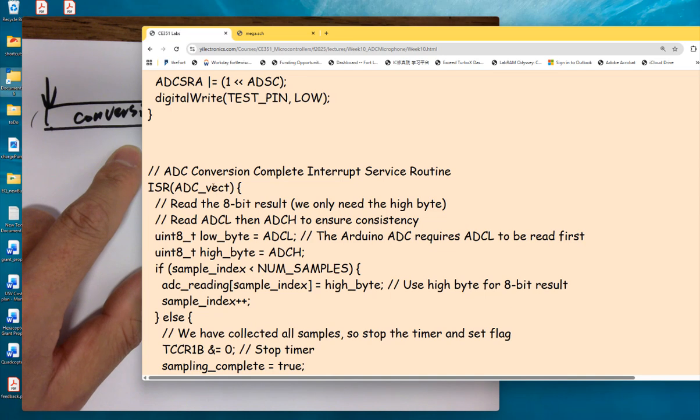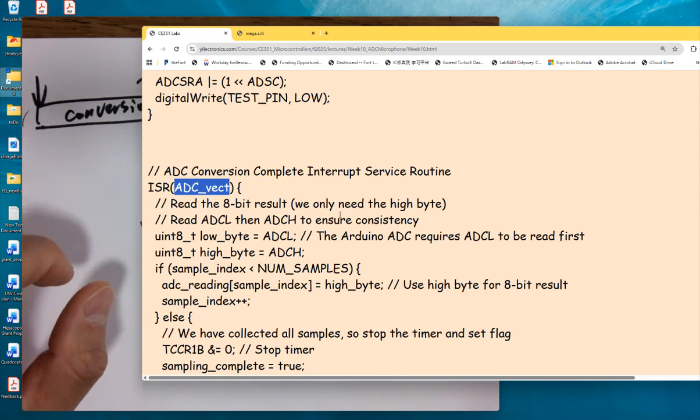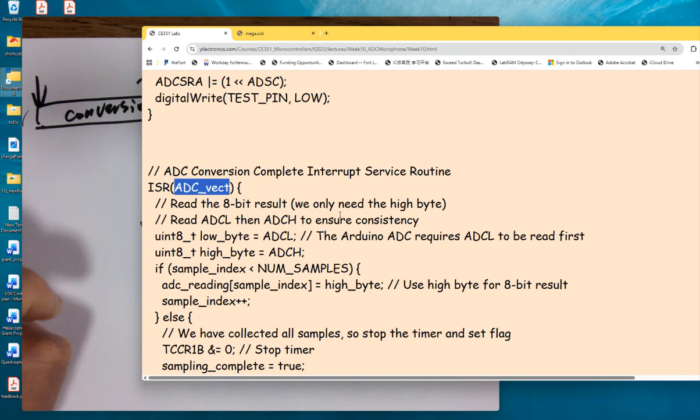So that's called the ADC completion ISR. There's a flag. We're not handling the flag, because the ISR will automatically clear the flag by itself. So we don't have to touch it. That's a good part of the ISR. We don't even need to know. It just enters the ISR, and after it's done, it clears it. You can also handle it yourself if you don't have an ISR.